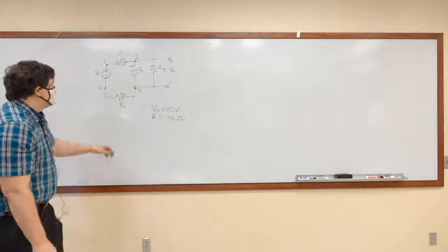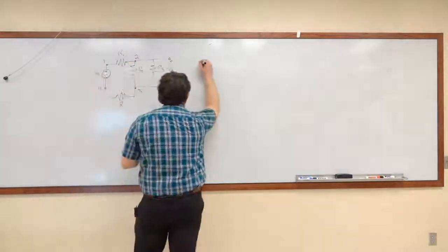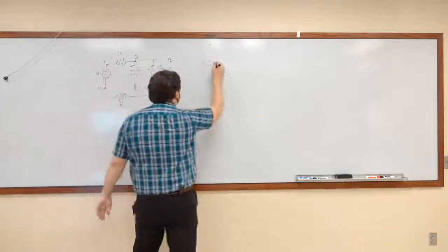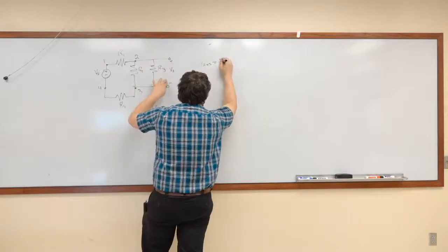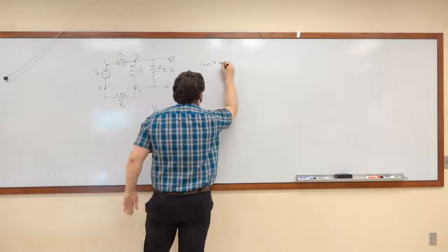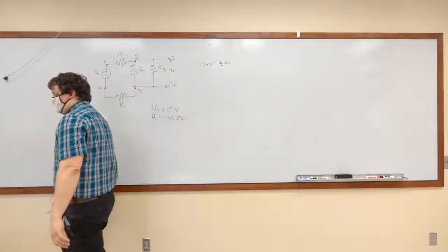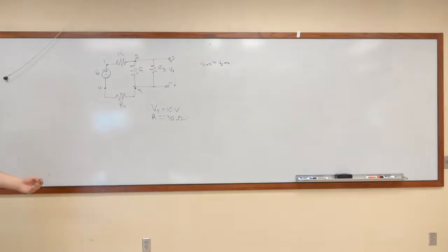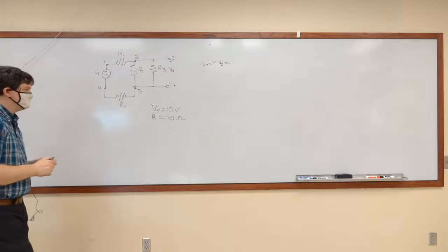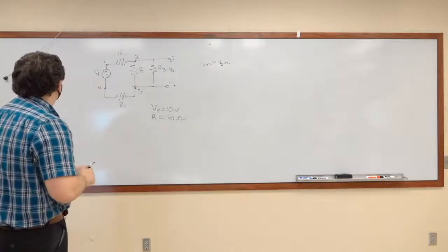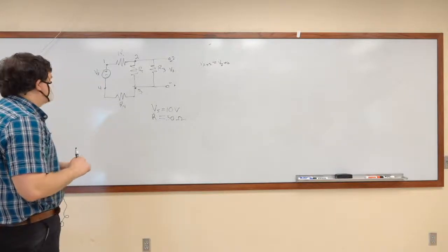So what we're going to do first is figure out what the voltage is between nodes 2 and 3, because that is the voltage between A and B, VA to VB. So if we know what both 2 and 3 are, we can figure out what the open circuit voltage is, just as this is drawn. Let me know if you're struggling to see my handwriting, because I can write a lot bigger, or I get to use a different marker. Okay. So voltage 2 to 3 equals voltage A to B. Awesome. Well, we got to step through the circuit and figure that out.